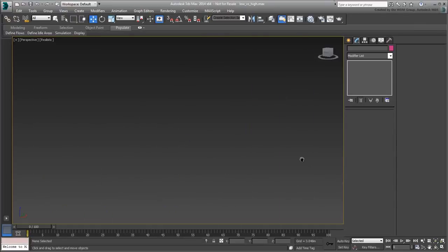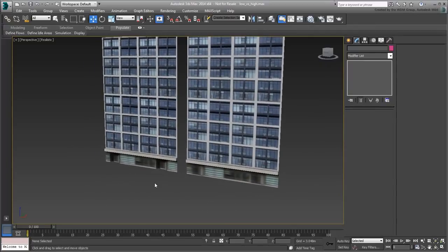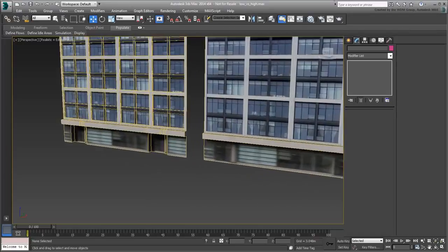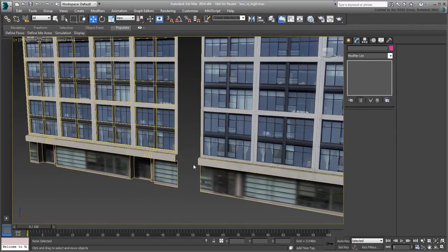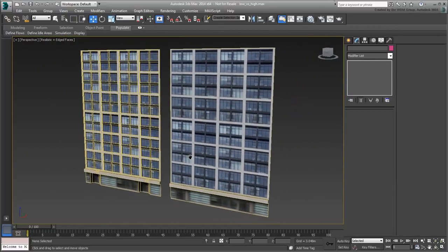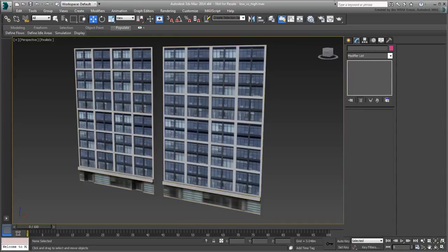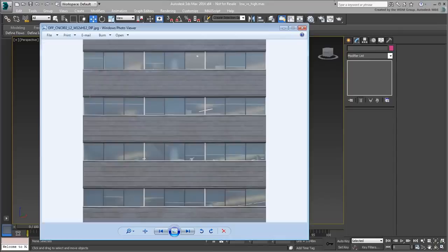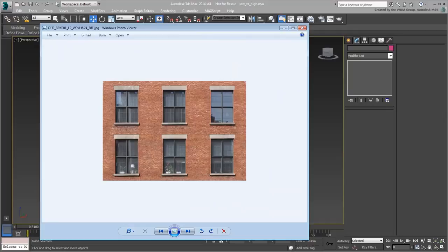This is often needed when dealing with multiple buildings in a scene. High polygon buildings would certainly look better, as they would have more volume detail and more depth. However, you won't be able to afford to have too many and still keep the scene manageable. Since you will be mostly relying on textures to complete the illusion, the first thing you need is to create a texture library. These are certainly available to purchase commercially, but you can also create your own. There's a startup library provided to you with this tutorial, and you're encouraged to add to it.